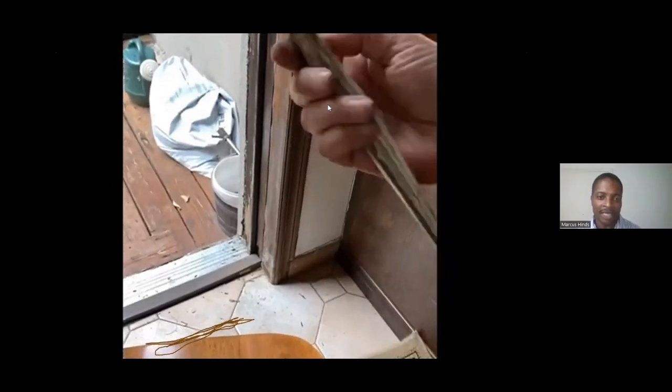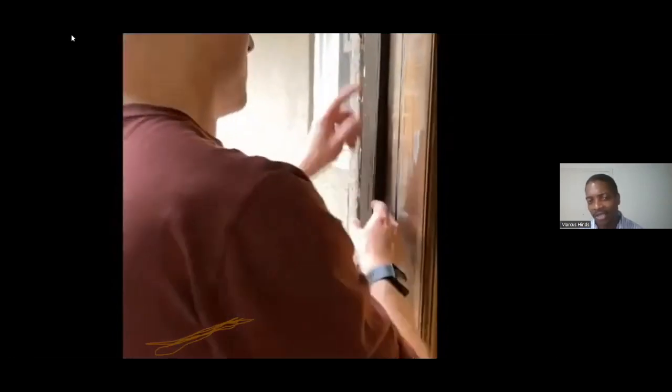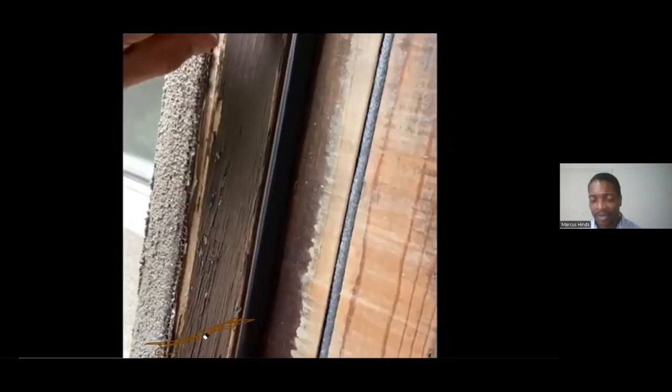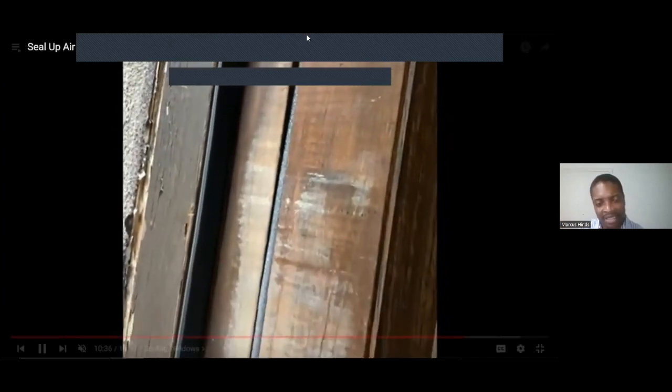So you can see now he's looking at the old stopper, replacing it with a new stopper, and then essentially using a permanent kit to install that door seal. One of the main things to think about when you're doing this is that any older pieces or older kits that may be there already, you don't want them to get in the way of the door. So you may have to glue those down, or you may have to caulk those down to make sure they're not in the way, because over time, closing and opening the door will drag them out, or break them up and bend them up and things like that.